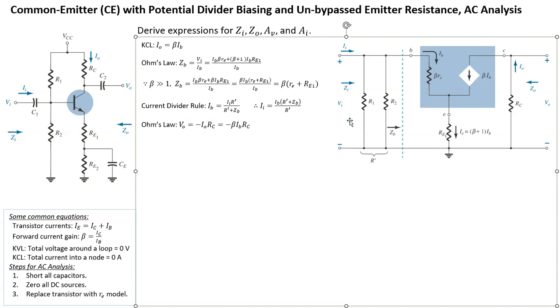All right, so let's have a look at VI. VI is the input source, input voltage. And again, we're just applying the same principle as earlier for VO, i.e. Ohm's law. So what we're going to get is VI is going to equal II, that's the input current going into the network for VI, times the combined impedance of all three things that we have here.